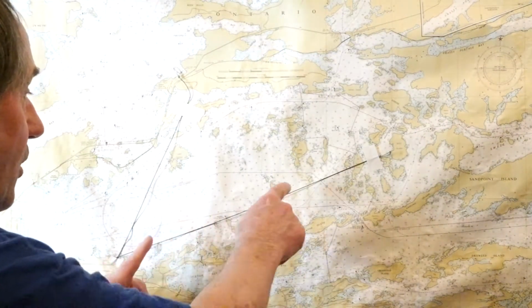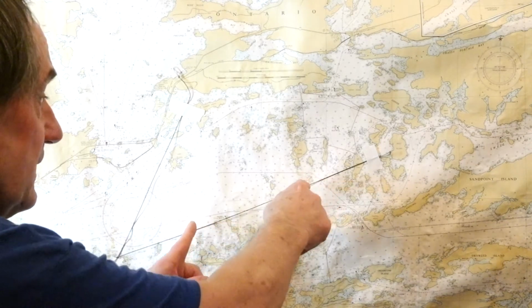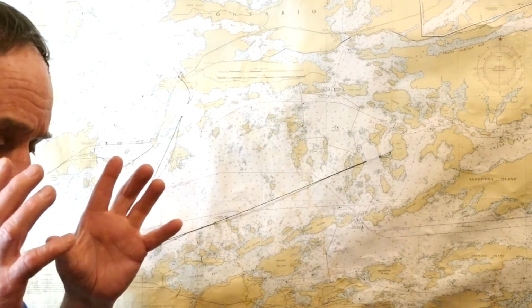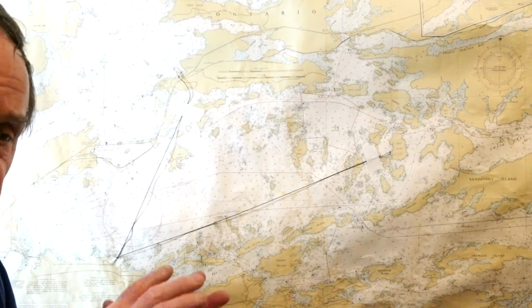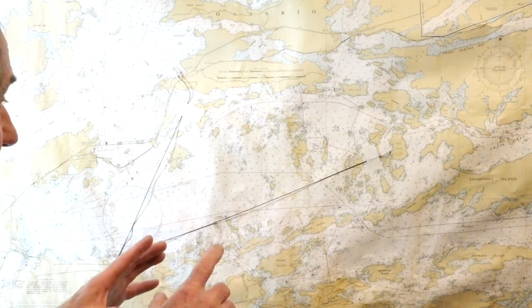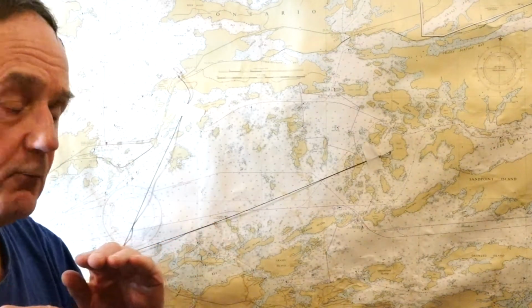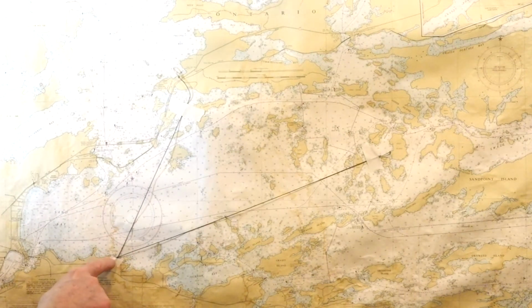poles. I'll be sinking poles and freezing them into the ice, which will be a very strong base. They won't move at all once they're frozen into the ice. And then we'll be setting up targets on the poles to sight with an auto level back at the reference spot.